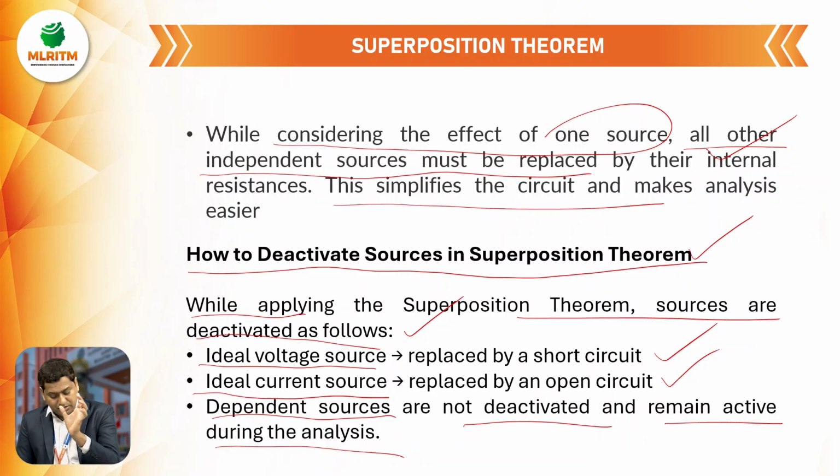Voltage source is replaced by short circuit, current source replaced by open circuit. The dependent sources are not deactivated; they remain active throughout the analysis.